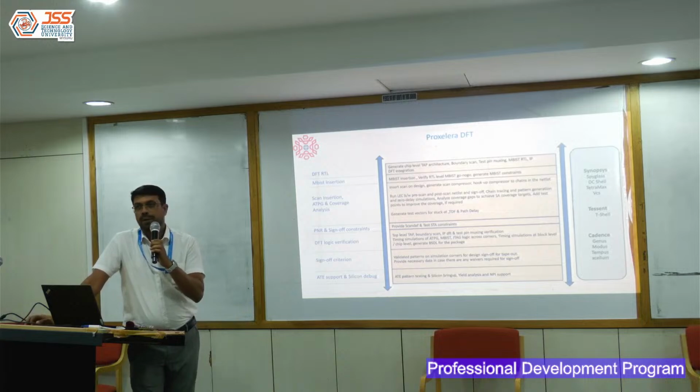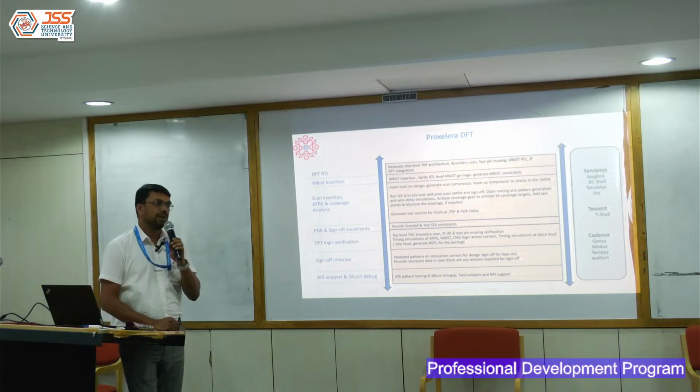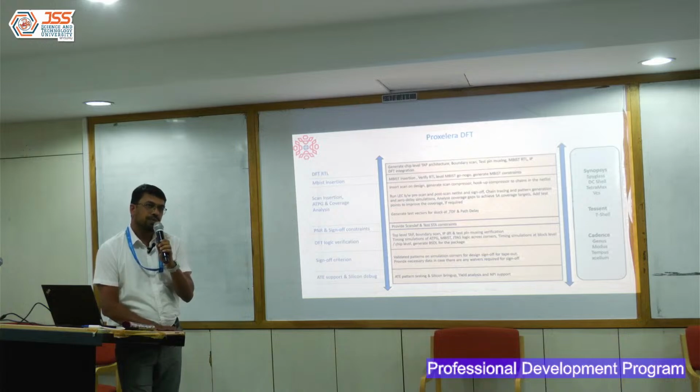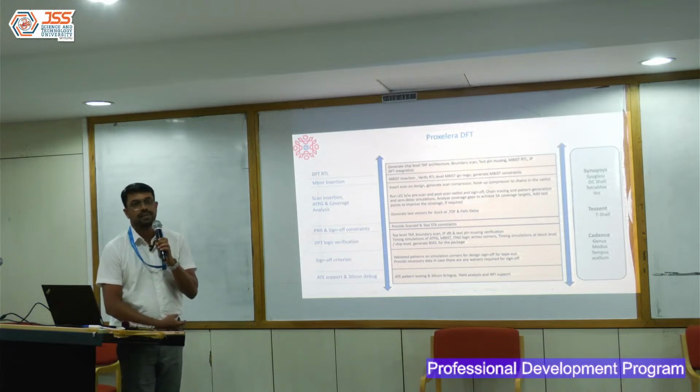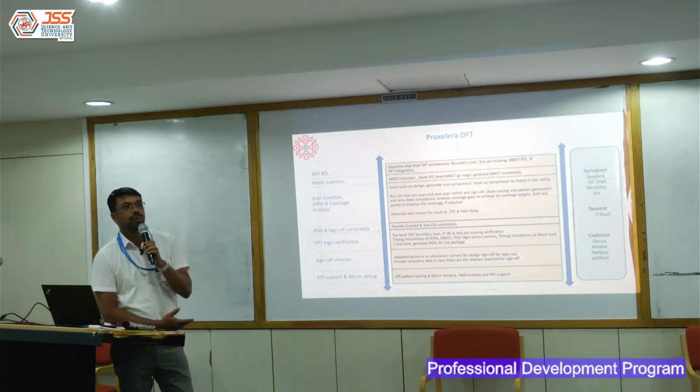So you might have studied about stuck-at, transition delay, bridge fault, right? There are different fault models available. So basically we test for those faults. This is just an introduction to why I'm stressing so much on the test, because we have to meet the quality needs. If we don't meet, as I told you, it's going to be a business loss.